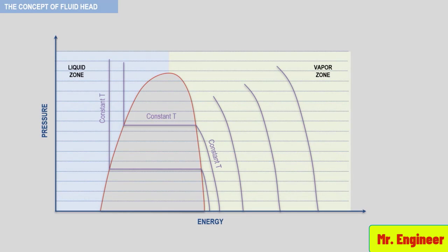This figure presents a typical Mollier diagram plotted pressure versus energy. A Mollier diagram can be drawn for any pure fluid or fluid mixture. Usually, Mollier diagrams are prepared only for pure fluids, since any change in fluid mixture will require a new Mollier diagram to be prepared. The Mollier diagram can be used to determine the head required by the process system for any liquid, saturated vapor, or vapor compression process.